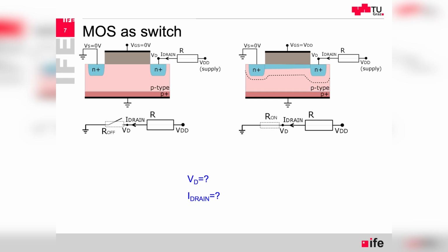On the left, we can see the off-state switch, where there is no channel and we have a certain off resistance. It's also important to have this off resistance as high as possible. And here we have to point out that if we buy solid-state switches in a catalog, they will never be as good as mechanical relays. The off resistance will be some hundreds of megaohms, but there will still be considerable leakage current through. So it's not a perfect switch by any means.